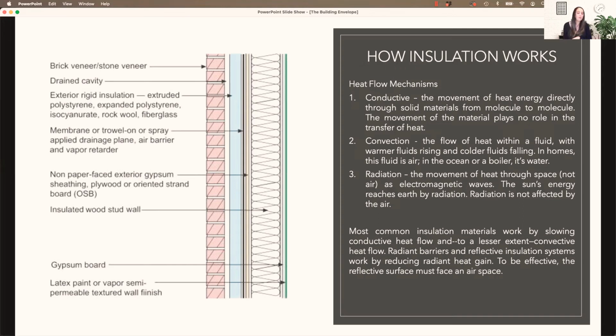There's also blown-in insulation, where you can actually take insulation and blow it into the cavity between the studs in the framing. And that can give higher insulating values. And then there is the expanding foam insulation, where you spray it in and it expands and adheres to everything around it. So it depends, again, on the climate zone what type of insulation you might see in a project, but essentially they all work the same way. They work to, like I said, either keep heat in or out.